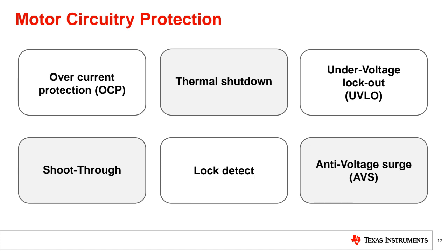Most important one, shoot-through protection, remember. Shoot-through protection circuitry helps prevent both MOSFETs in a half-bridge circuit from being on simultaneously, which would result in a current short. High side MOSFET and low side MOSFET run at the same time, it's called shoot-through.